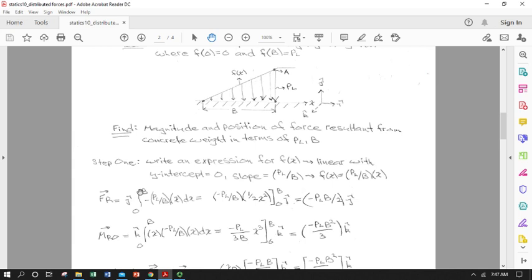Okay, so let's define a bit of force. So here's our width of any given little force element, and here's our force per unit length, and we know it's pointing down in our j hat direction that we just defined, and let's add them up from 0 to b, from our x equals 0 at the beginning of the ramp to our length b, where we're not concerned anymore, not attached to the porch maybe. So we'll integrate that function. So those of you who are interested in learning to integrate, here's a step through a very easy integral.